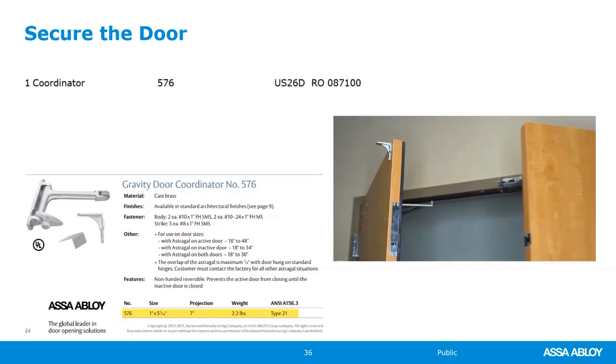Would anything change if this was considered high hazard, or did the hardware they chose meet those requirements? Yes, what would change if this were considered high hazard? If this room were big enough to have enough med gas to be considered high hazard, then you're required to put exit devices on this pair of doors. That's the change. Any high hazard, regardless of occupant load, and typically there is no occupant load in a high hazard, so you would be required to have exit devices on that pair.